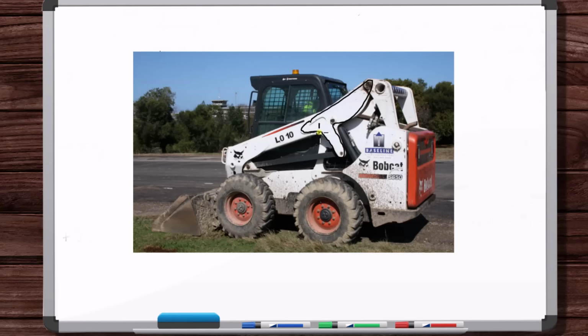So we're not taking a group of connected components, we're just taking one component. We bring it into empty space. We remove it from being connected to the machine here and bring it into empty space. But now that we have it in empty space, we want to add all of the forces to it, so that even though it's in empty space, it's still an equivalent representation of how it was connected here, right? So we want to bring it into empty space so we can analyze it.